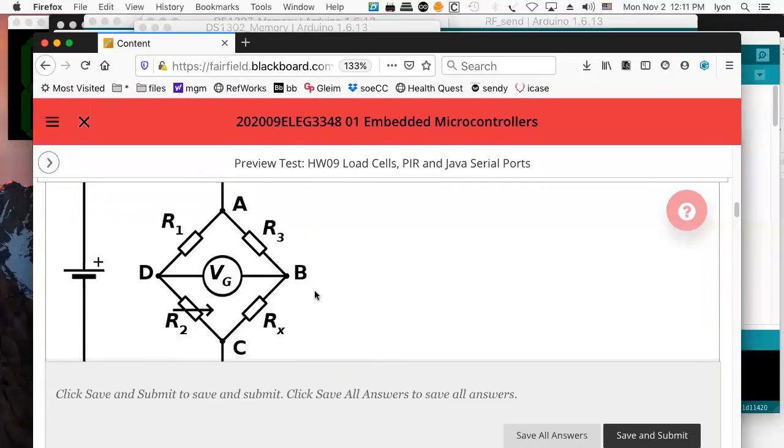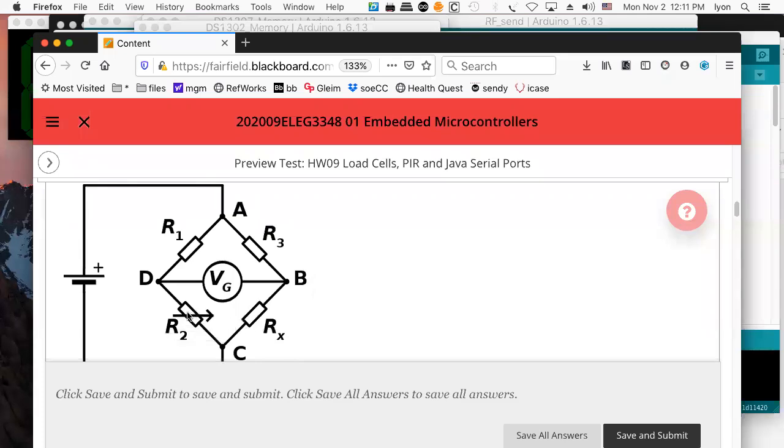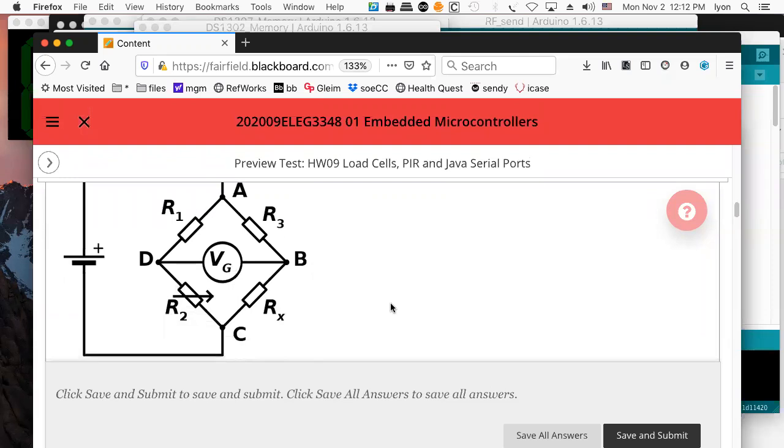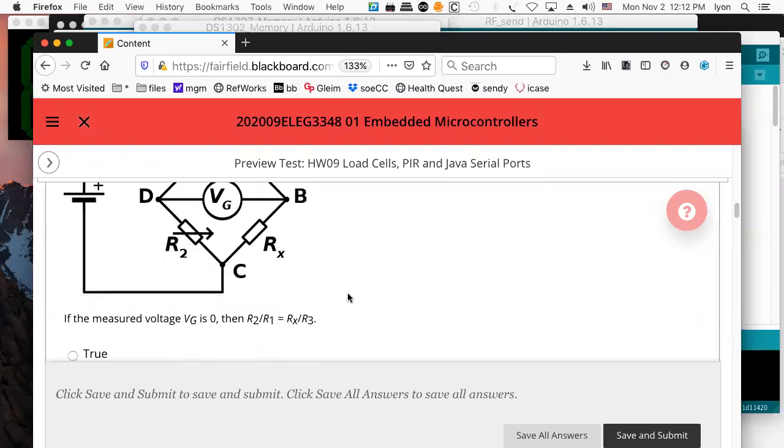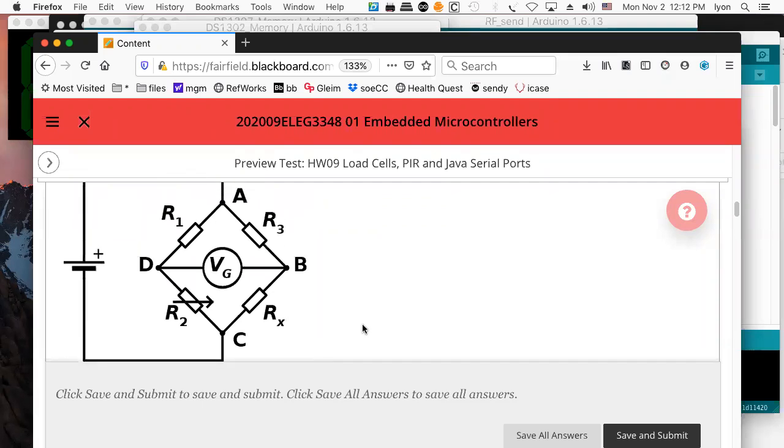And here's an example of the Wheatstone Bridge. So what we'll do is we'll have a calibration resistor, which is tuned, an unknown resistance in here, and two known resistances. And we'll adjust these so that the gauge, the voltmeter in here, is registering 0. And then when this is under compression, it goes one way. If it's under expansion, it goes the other way. It's the opposite of compression, I guess. And so that's essentially what you're trying to do when you're creating a load cell.